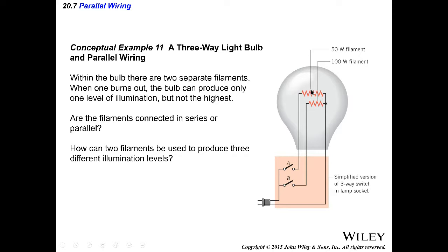So therefore this is 1 over R plus 2 over the same R, because this R is double that. And therefore now the net resistance of the whole thing is smaller because it's 1 over R plus 2 over R. Therefore the net resistance is a third. And since it is now smaller, now the power is the same V squared over a smaller R, therefore it's brighter. Are you following me now?